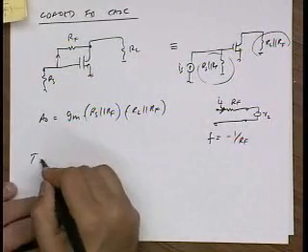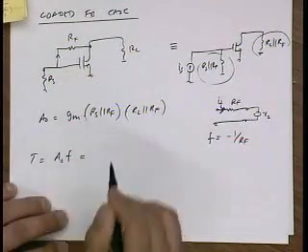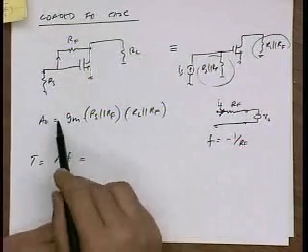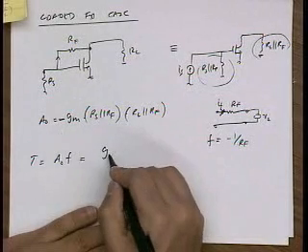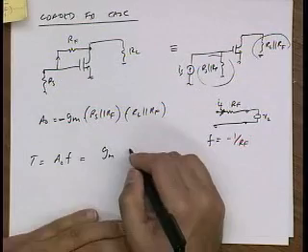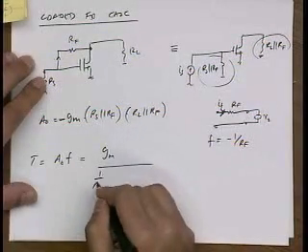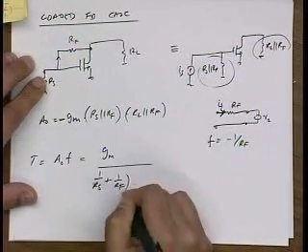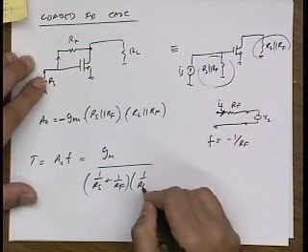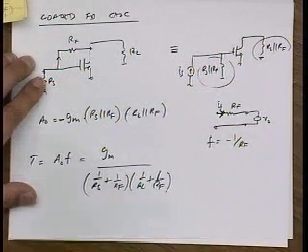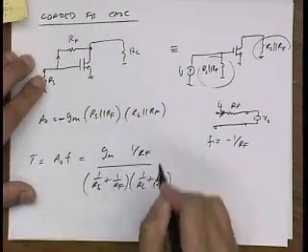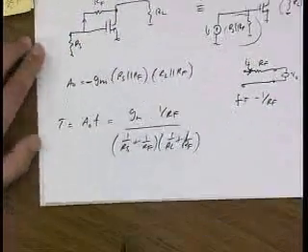And so now the loop gain is just this times that, and this is of course negative, so I get positive overall. Let me write this as 1 over RS plus RF, this as 1 over RL plus 1 over RF, and this is 1 over RF, right?